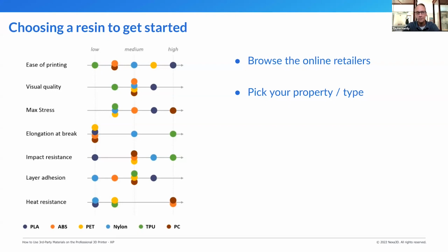In the reviews, it's going to tell you specifically what kind of quality you should expect out of the resin, but also a lot of times people take the time to go through and give you specific parameters in which you would want to run the printer at, regarding exposure time, base layers, but also the manufacturers have uploaded that a lot to the profiles that are on these open source pages.